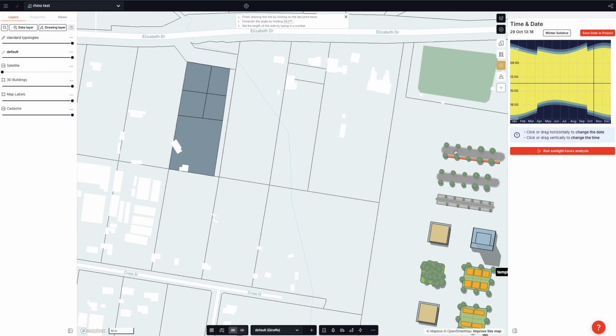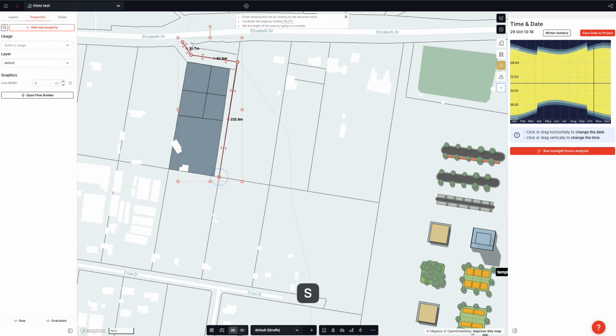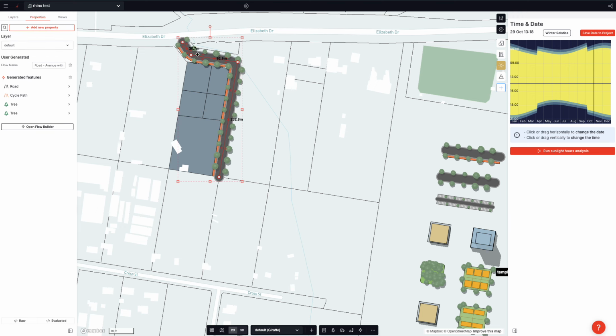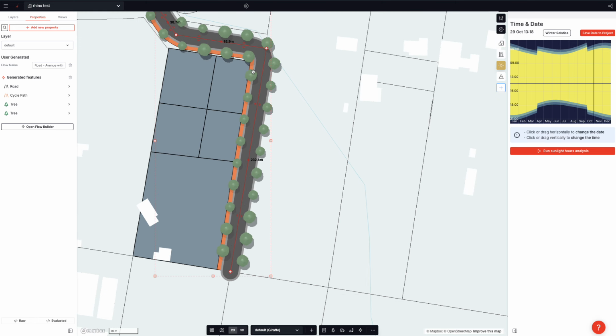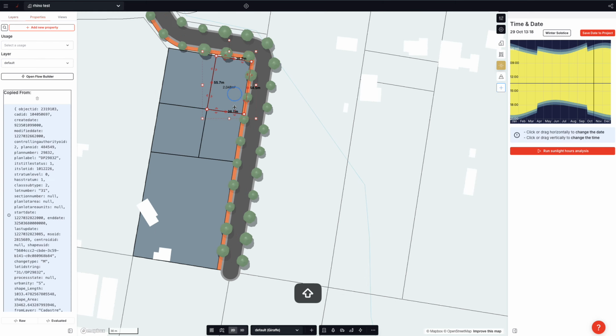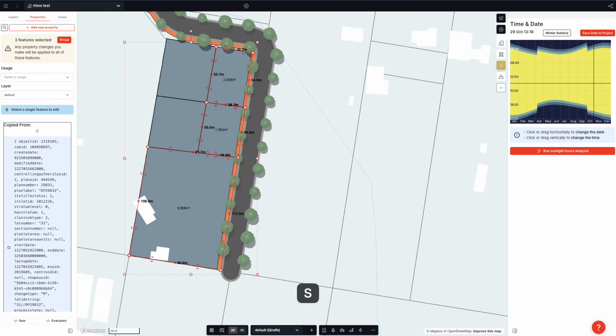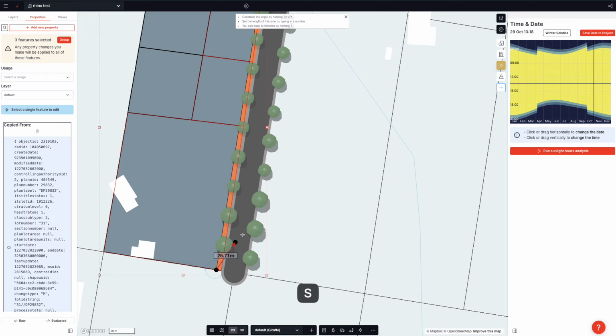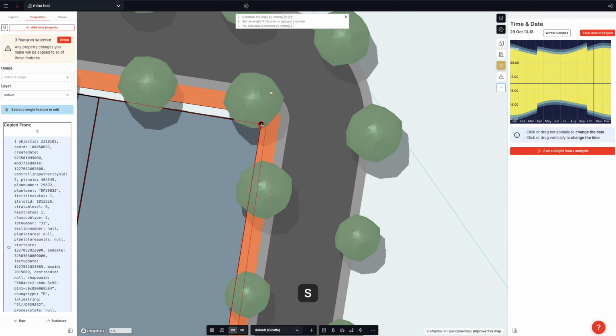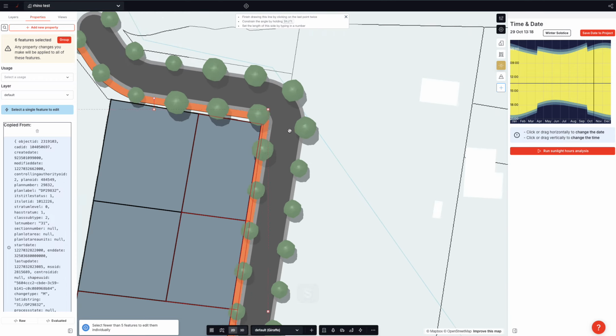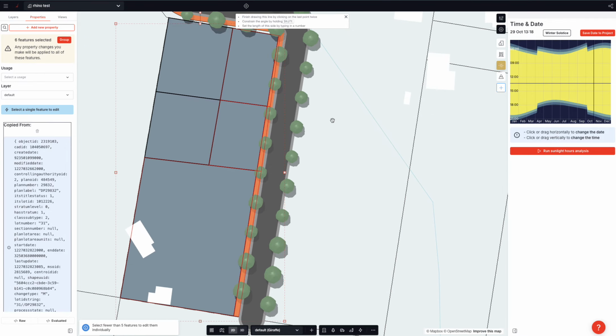And then I'm going to choose this road. So to do that, I'm going to use the line key, come in like this, come halfway down and go down. And then I'm going to click Y and select this road. Now this road actually has a cycle path, so it's slightly wider than 10 meters. So I may just trim this back. So I hit the X key, snap to the edge of that cycle path there, and those all trim off.